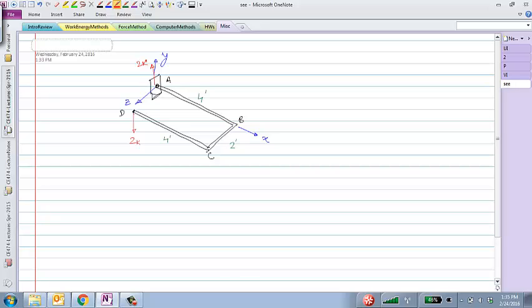Think about it maybe a little bit physically also. If you have a bar that is bent into that shape and you're holding it on one end and applying a load on the other, what kind of moment would you be applying on the fixed end? Torsion. Would there be any bending moment also? Yes? No, there won't be any bending moment, right?